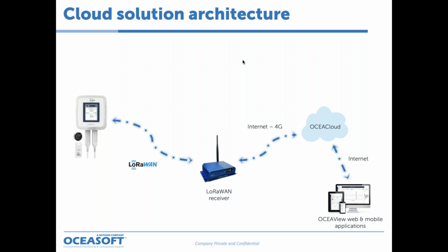If an alarm occurs, such as a high temperature excursion, alert notifications can be sent by email, SMS text message, or voice calls based on alert strategies that you can define in the system. We also have wireless sirens to grab your attention, and dry contact alert relays that can interface with an existing building alarm system.